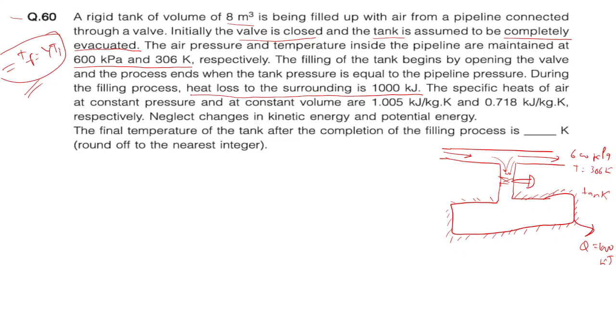Okay. So this is one type of open system here, correct? Because from here some mass is coming in, and let's suppose this is our control volume. Some mass would be coming inside and no mass is going outside, right? Because it is completely sealed. So m exit is 0. Keep that in mind. Some mass would be coming, that is for sure.